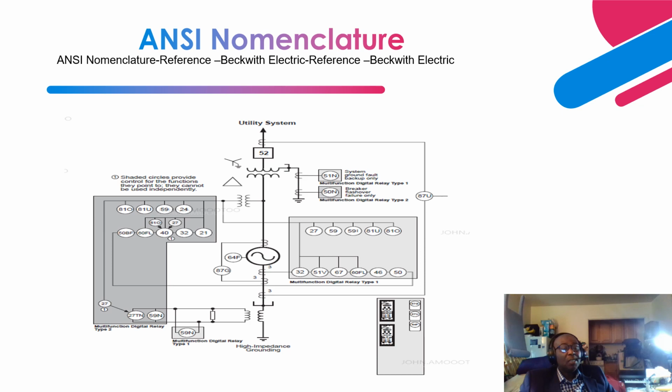generator. Similarly, for 81U, which is the under frequency element, let's say you have a 60 hertz nominal operating frequency of a generator. The manufacturer is going to allow you a tolerable range of 58.5 hertz to 60 hertz. Beyond 58.5 hertz, the manufacturer will definitely put a timing in it and trip the generator offline.